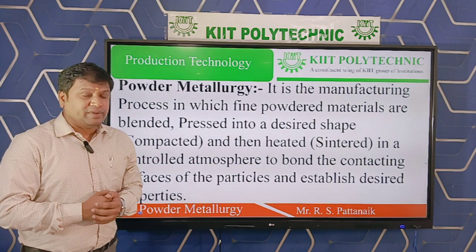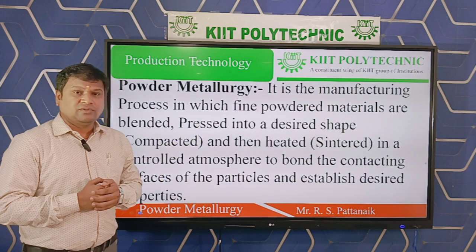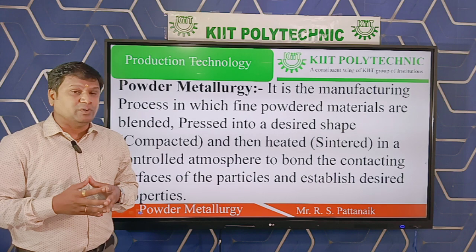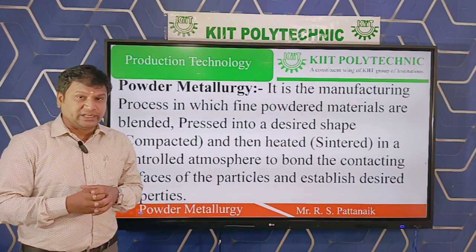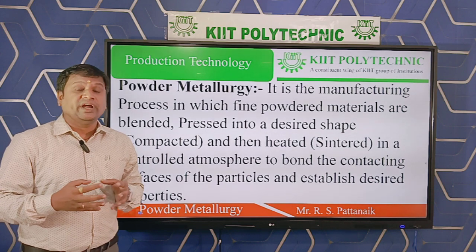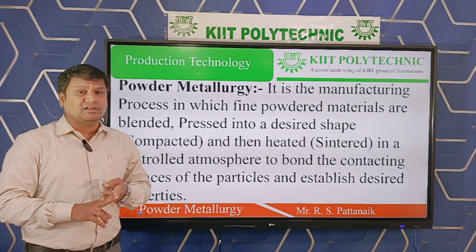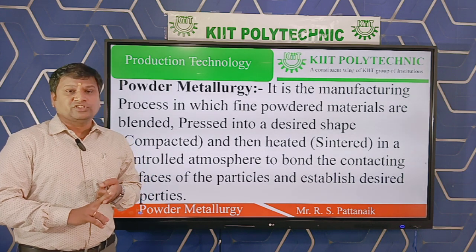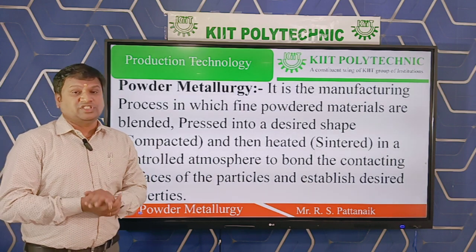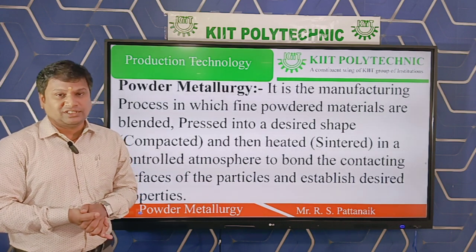There is an important piece of information. In the sintering process, when the compacted metal powders are bound together to produce a new component by interparticle bonding, the temperature of this sintering process is always kept below the melting temperature of the base metal. This is the basic principle of the powder metallurgy technique.